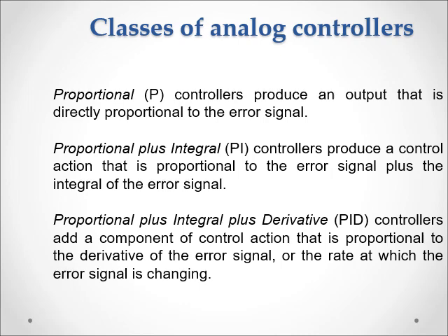In many cases you only stick to a PI controller, but sometimes you may need a PID controller. With the D in PID control, sometimes you will see that if you have a set point, initially your output will overshoot the set point and then come back, and then it will oscillate, and then the output will settle down around the set point. How fast you want to achieve this state of steady state condition depends on the D value.